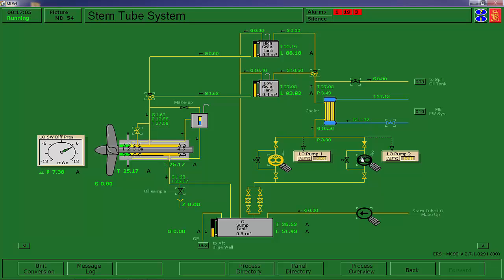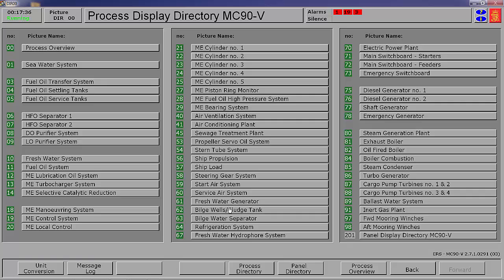Now, if you put them in automatic too quickly, because you're having to fill this tank up, what will happen is, because of the low pressure on the output, it will automatically start another pump. So you want to wait until this is overflowing and then put both pumps in automatic. Putting only one pump in automatic doesn't do anything. They both have to be set up so that it can shift from one to the other depending on pressure.